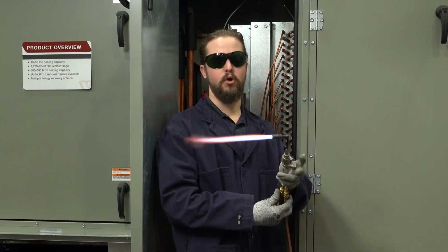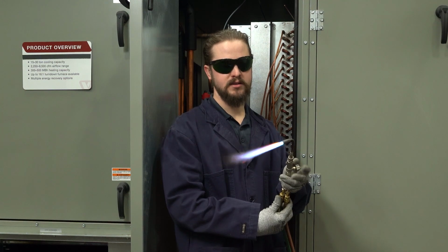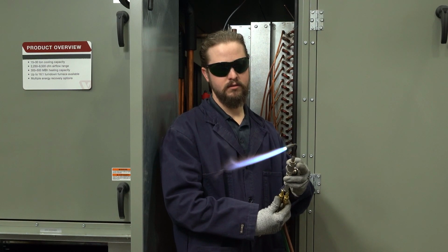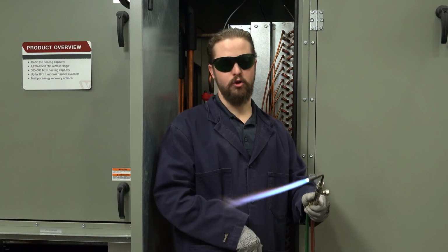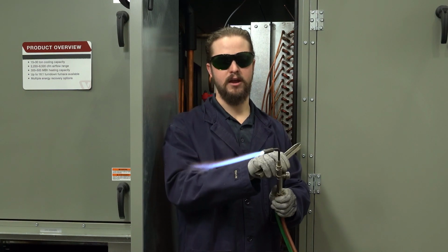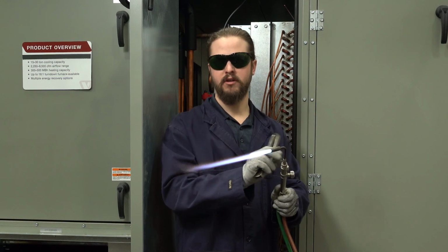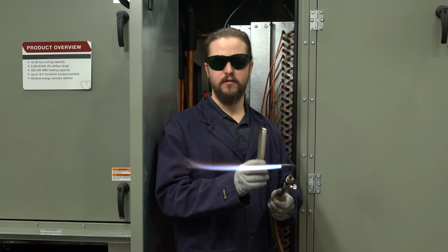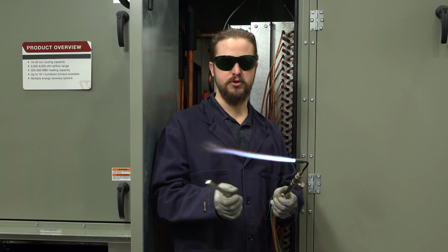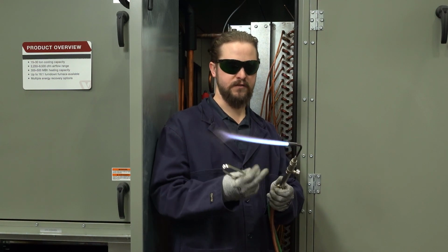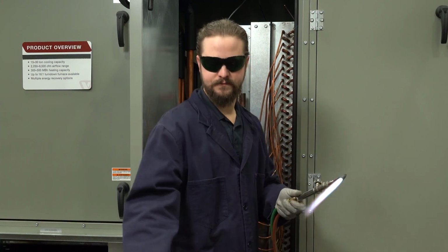So it's actually more ideal to just create as balanced of a flame as you can. And with this rosebud torch that I'm using here, I'm really just audibly listening for a quiet flame. That's kind of what we're looking for here in this case. In the field, you'll probably be using a turbo torch or something like that, where you have a little more control on the length. But this full-size torch, this is what we're looking for.